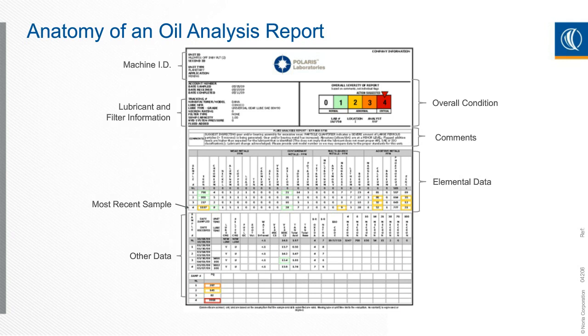Also be aware of any test standards and calibration references, anything that tells you what they are using to do the test itself, because it might be different compared to what a different laboratory might be doing. And also look for specific elements tied to additives and contaminants and wear debris, and also look for any other confirmatory indicators around that.